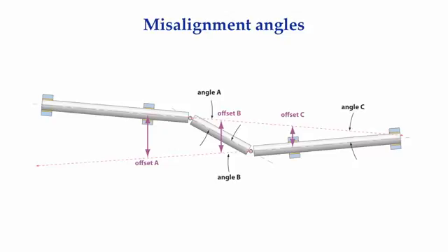Angular misalignment expressed in mils per inch traces its source back to the face and rim alignment measurement method, where you measure the face of a coupling hub, typically over a 10-inch diameter, and you observe the change in distance between the coupling hub faces from the top to the bottom or from one side to another. But the face and rim alignment method is the subject of another tutorial, and the question of whether a minus 1.5 mils per inch or a plus 1.5 mils per inch means that the coupling hubs are closer together or further apart from the bottom to the top will be discussed at that time.